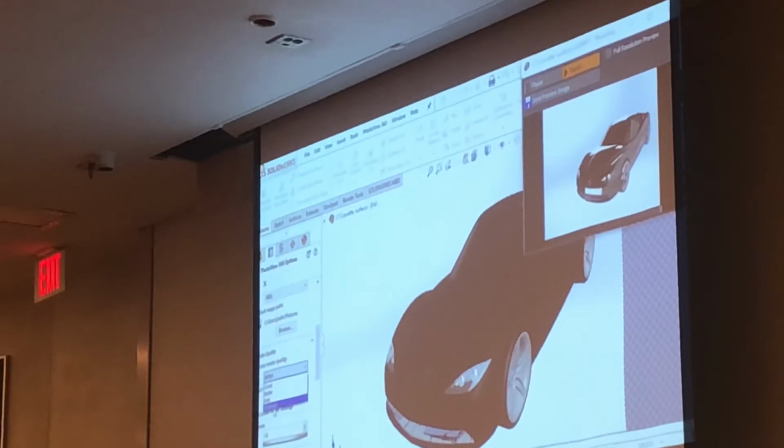If we set the quality setting too low, what would happen is the ray of light would come in here and get partway through and then just give up and stop calculating. So the effect of that is it creates a black hole in your image. If you ever see an area in your image that just looks like it's missing, it's black, you may just need to come in here to your quality setting and set that to a higher level, okay? I'm going to go ahead and set this a bit higher for the final render.